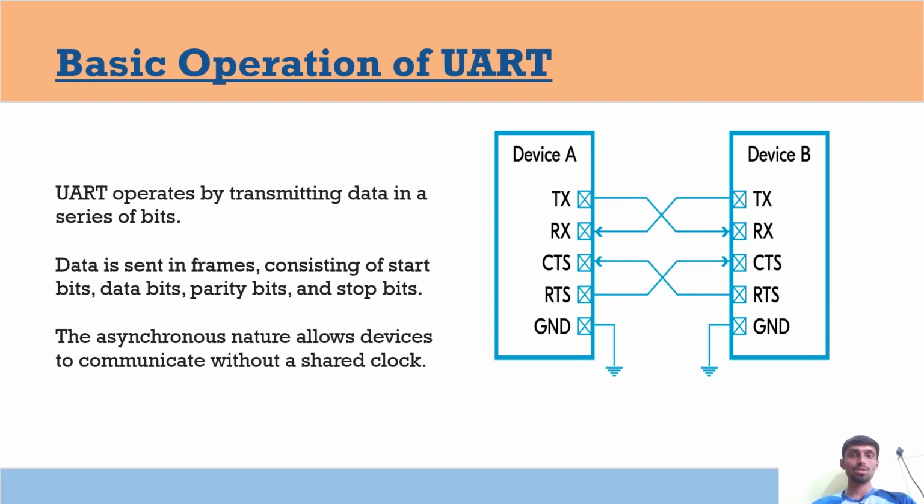The basic operation of UART is transmitting data as a serial stream of bits, and data is sent in frames consisting of start bits, data bits, parity bits, and stop bits. The asynchronous nature allows devices to communicate without a shared clock.